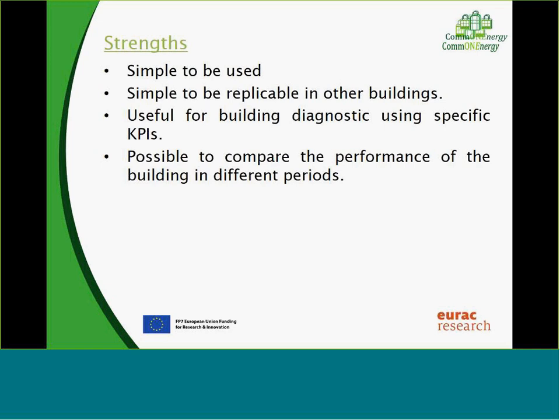Something I would also like to add about the key performance indicators is that in this continuous commissioning tool, a big part of the work was really about defining good key performance indicators. We managed to define new key performance indicators that take into account not only the energy consumption, which is a basic and always useful type of indicator, but also how well that energy has been used. So we managed to put together in the same indicator the goal for which the energy has been used.